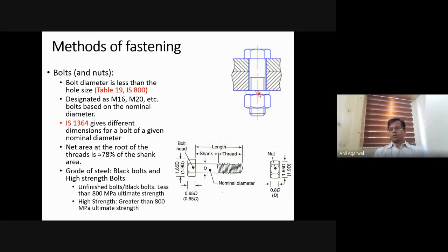Okay? So what does the washer do? Here the washer is not really serving the purpose that it is supposed to, but basically what happens is that sometimes this hole may be slightly too large for the nut or the bolt head. So basically this area here provides the bearing resistance. So the tension that you apply, or the amount of twisting that you apply to the nut, leads to development of tension in the bolt and development of compression in this plate. Now, sometimes what you may find is that, not only this twisting, when you actually apply the forces, your real life or working stresses or limit state forces, at that time also you may be applying some tension on this bolt.